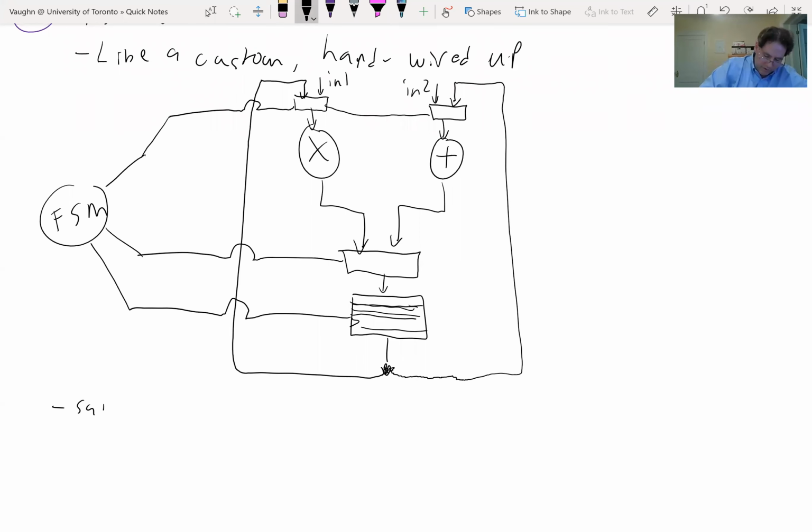Okay, so what's this suitable for? If you're designing a system, when would you use this instead of using some kind of streaming hardware? So let's say that you're actually going to build this for Lab 1. So you're going to build a shared operator design, which is basically this. It's a finite state machine controlling a data path. So we built here just two operators. We can do multiply, we can do add, and we can control them with a finite state machine, and we can store some temporaries. So when does this make sense to do instead of doing a streaming data path?